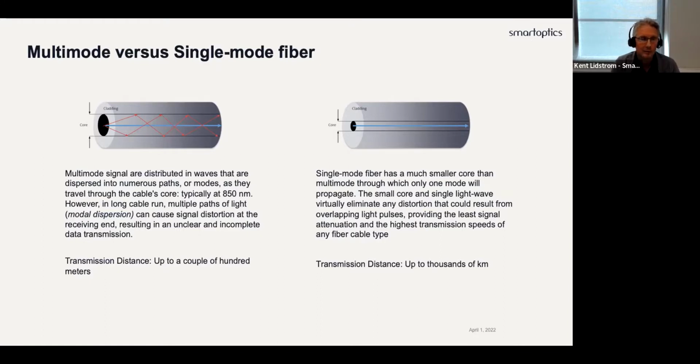And when the wavelengths are bouncing in different directions and different paths across the fiber, it will be distorted along the line. That means it's going to be difficult, if you send data with a very predictable 1 and 0 pattern, for the receiver on the other side to predict the data if it's been messed up too much.